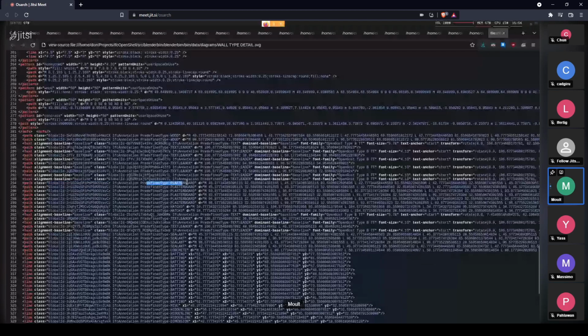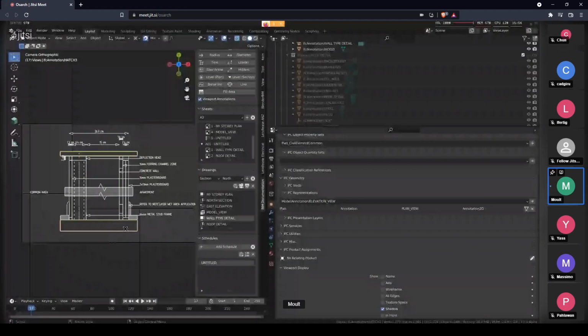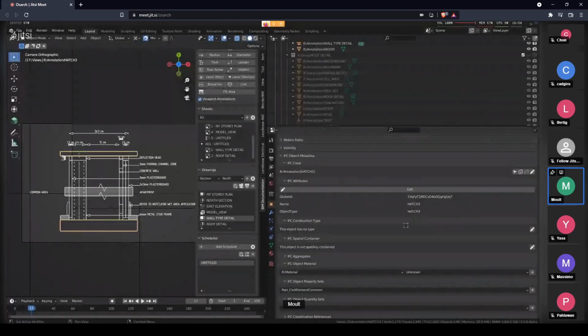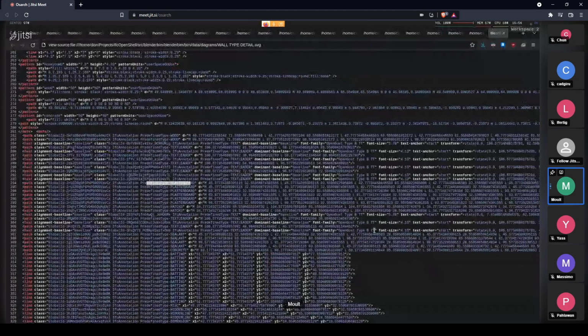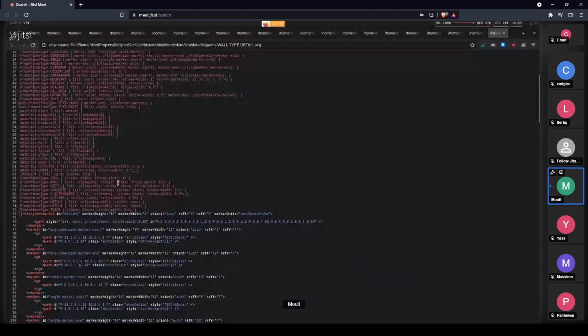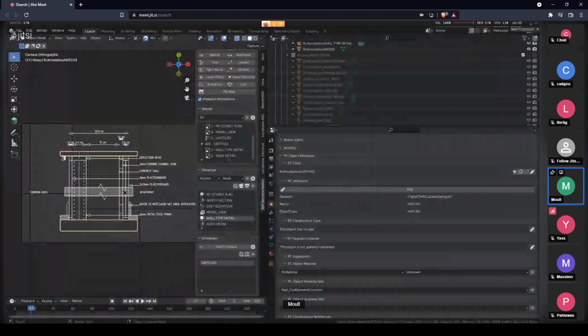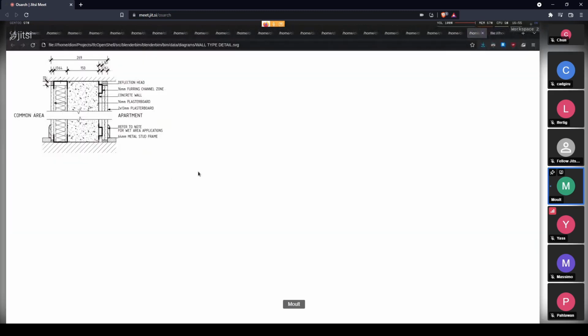So you can see how this object had a predefined type of hatch3, which means that it comes through here as that predefined hatch3, which I can then select in my CSS definition. I want hatch3 things to be filled with a diagonal fill, and no stroke outline. So that's how I end up getting this result.